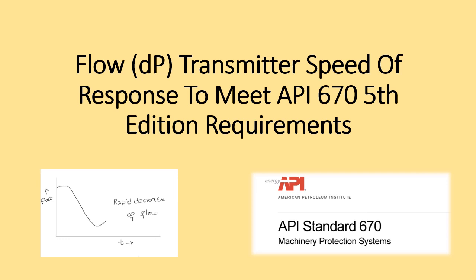API 670 is the standard for machinery protection systems, and in its fifth edition it provides specific guidelines about flow transmitter speed of response for the anti-surge detection system. In this particular lecture we are going to discuss the specific criteria of the DP transmitter used in anti-surge detection system.